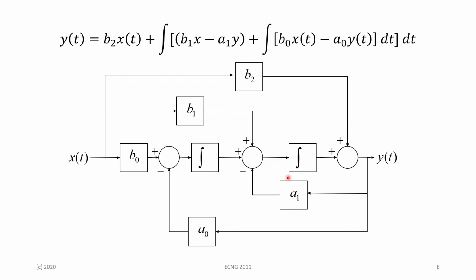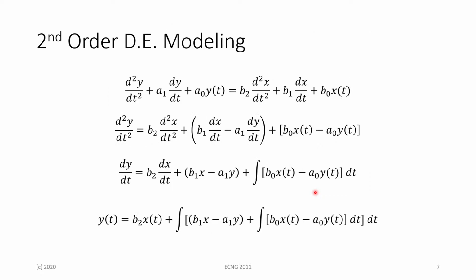Oh wait, hold on. Let's see. Differentiation can actually be represented on a block diagram, but I'm showing you this from the integral point of view because I need to transfer this into the S domain afterwards. It's a lot easier to work with integrals when you're doing the S domain. Oh yes, thank you for that correction. There needs to be another integral form here.